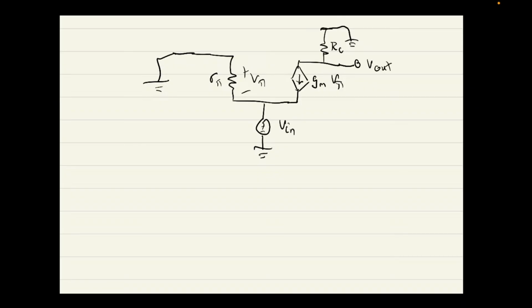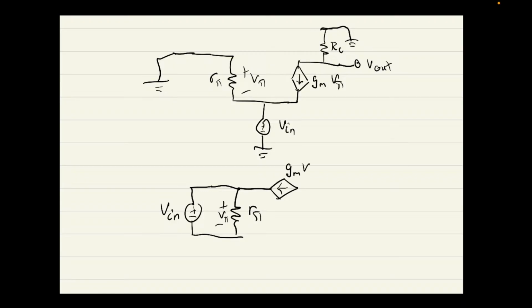Okay, so we've got the small signal model over here, and what we see is that V pi is 0, so we can essentially zero this out, pretty sure. Actually, no, I'm going to redraw this into something a bit more like this. Vn and plus minus V pi. Yep. Then we get